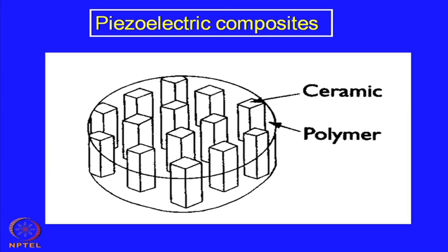So, one cannot stress them to a large extent, and therefore you have limited application. Because of the poor mechanical property, poor elasticity, you do not get to utilize the real piezoelectric effect in a whole range of stress. One way of avoiding it or improving the property is to make a composite with some polymer, and polymer may or may not have some piezoelectric property.